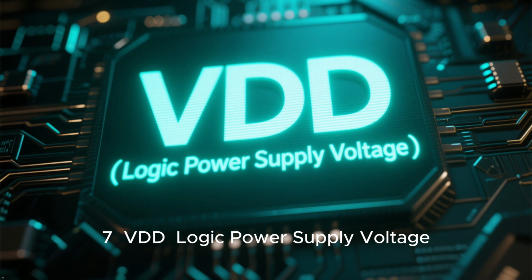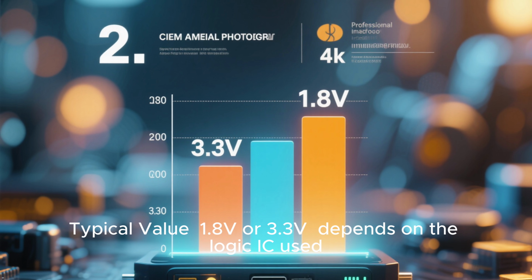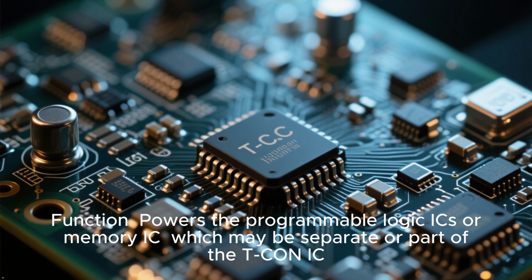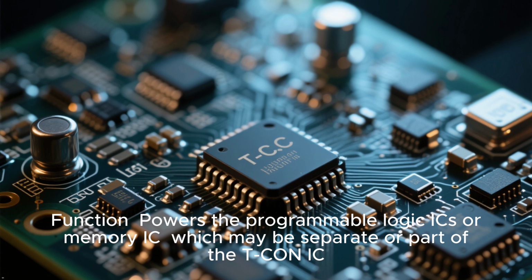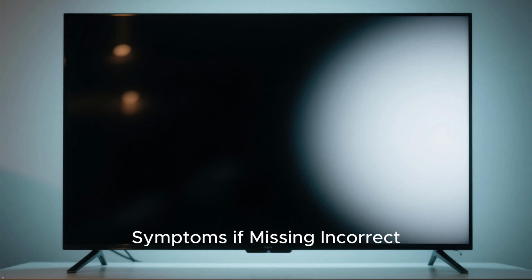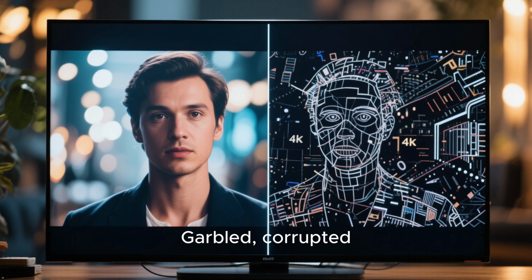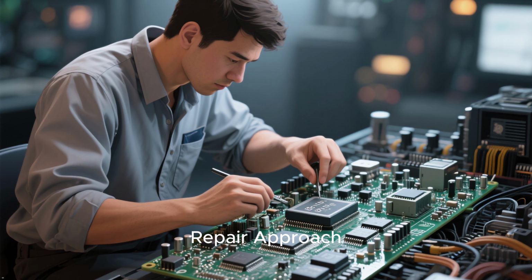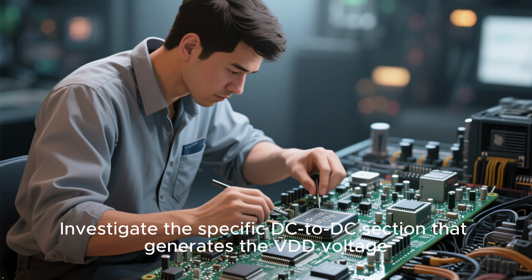7. VDD. Logic power supply voltage, typical value, 1.8 volts or 3.3 volts, depending on the logic IC used. Function: powers the programmable logic ICs or memory ICs, which may be separate or part of the T-con. This is crucial for the panel's brain or logic operation. Symptoms if missing or incorrect: no picture, inverted, upside-down picture, garbled, corrupted, or half-displayed images, dim picture. Repair approach: investigate the specific DC-to-DC section that generates the VDD voltage.